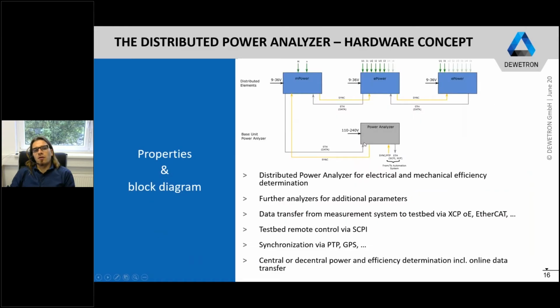And just to give you a specific detail, when we think about the three-phase system which we saw at the beginning, how may a distributed power analyzer look like for this example? You may have a base unit power analyzer here, which communicates with your testbed, which transfers the data over SCPI or XCP to the testbed, and which is controlled by the testbed by, for example, SCPI commands, and which also can acquire a synchronization signal from your testbed.